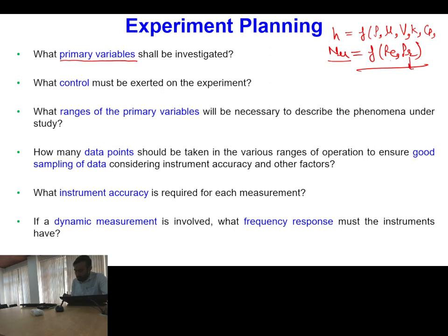Now in the Reynolds number and Prandtl number, you can see the definition of the Prandtl number is mu Cp by K. Now you have to fix whether you want to do your experiments with air, or with water, or with some other fluid, say some refrigerant. So you have to decide what your requirement is. You need to calculate the heat transfer coefficient for air, water, or any other type of oil or fluid. Once we have fixed the fluid, the values of these parameters are frozen.